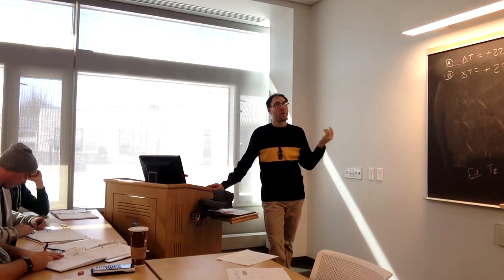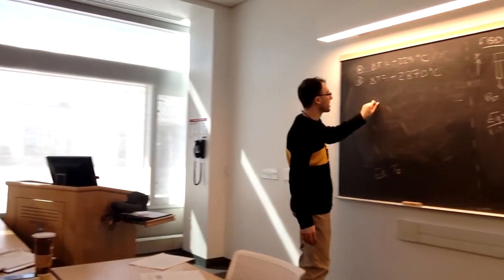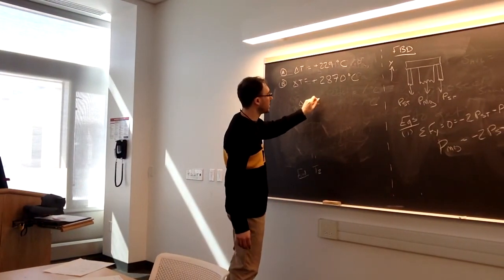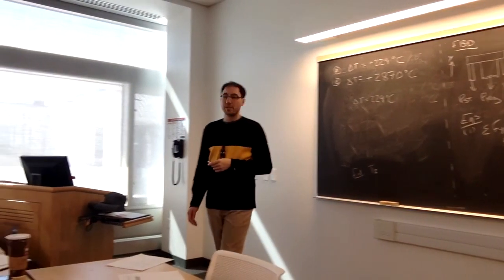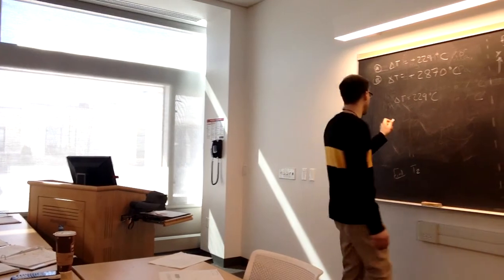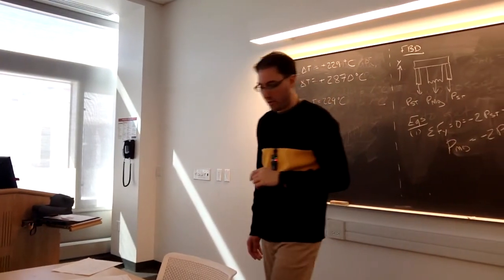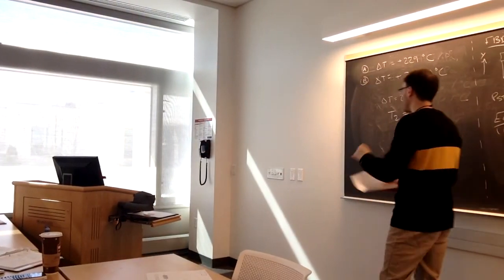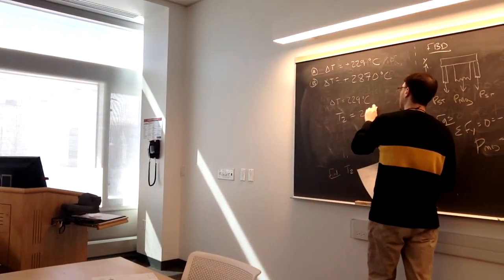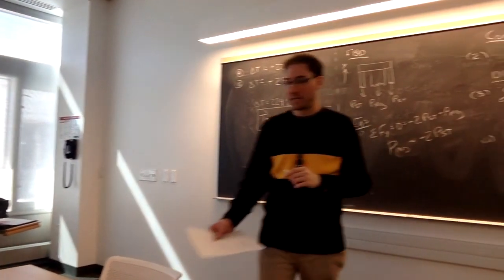Right, so we are looking for the lowest temperature. So the delta T that will cause the first one to have 12 megapascals of stress is the 229 Celsius. So if we add to our original temperature, T1 is 15, we get that if we raise the temperature to 244 C, the steel will just have 12 megapascals of stress.